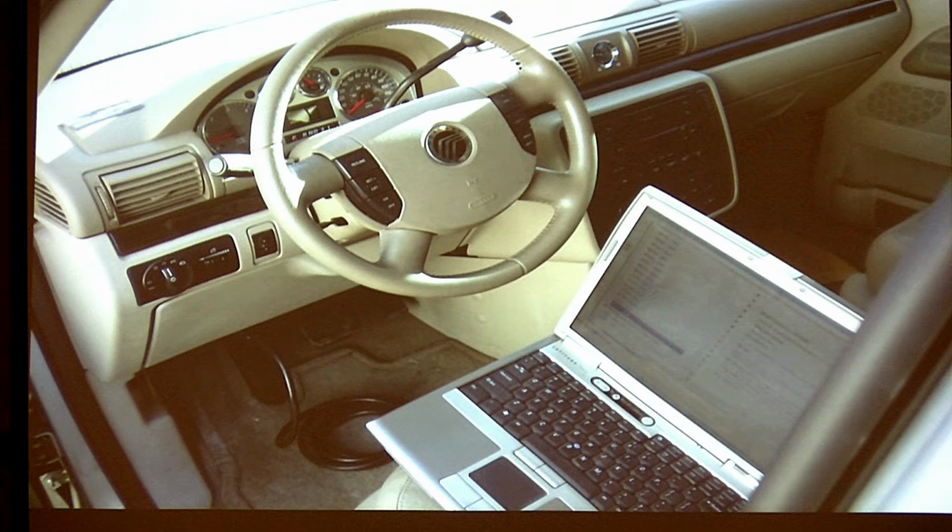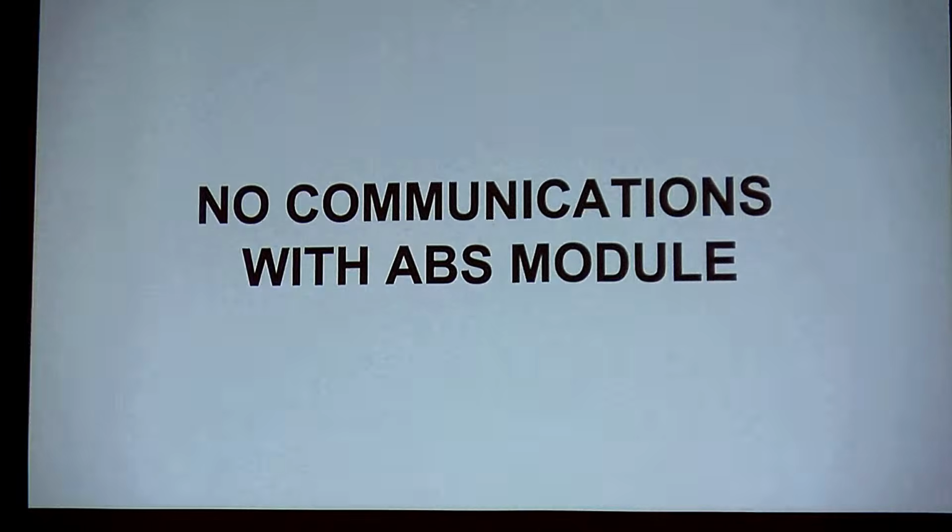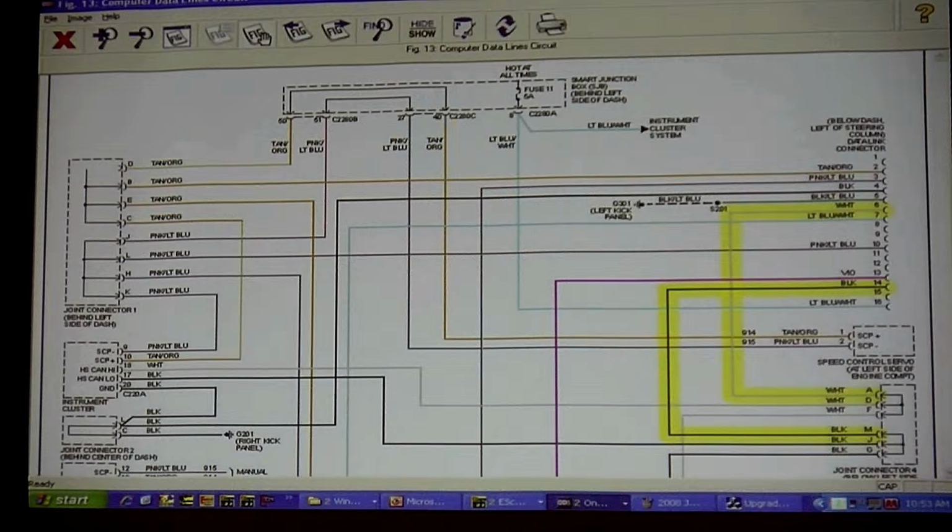So first thing I'm going to do, I take my scan tool. Again, this is a factory scanner. Not that you need that. You don't. It's just helpful because then I know whatever doesn't communicate, I'm not second guessing. I just know it can talk to it. And anytime I'm using just a generic scan tool, you're just not sure.